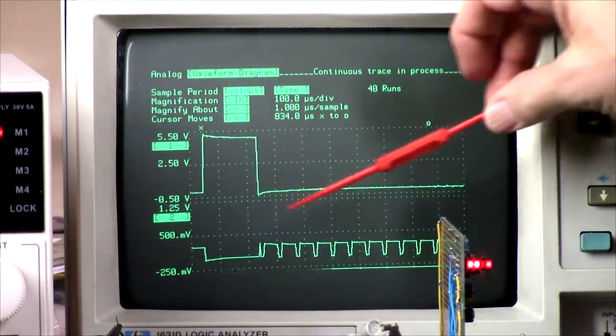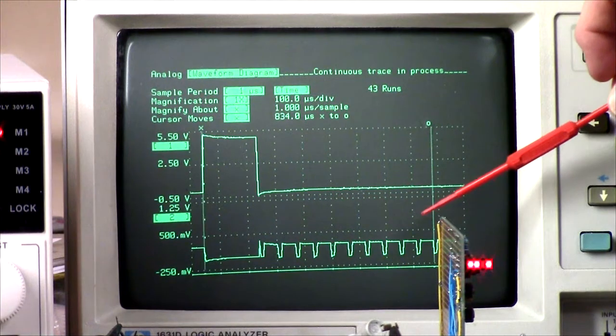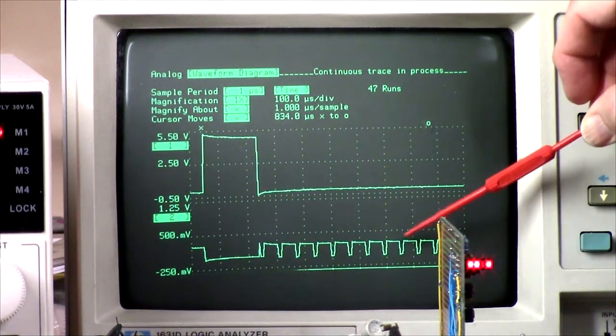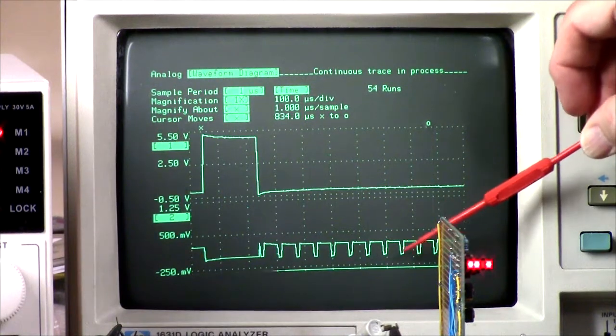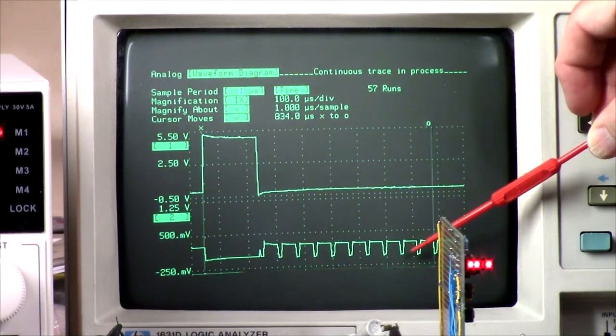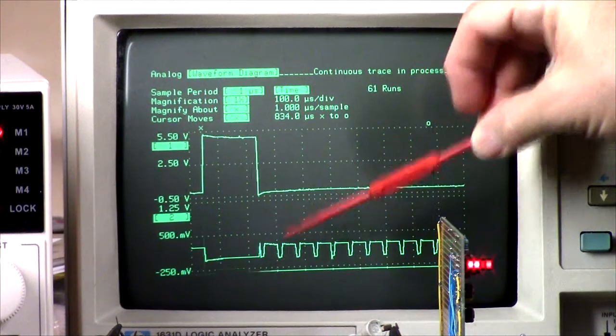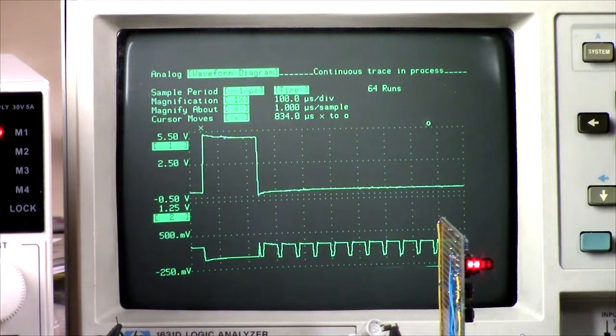So you can see here, we're at about 0.3 volts here, which is black level. And then the 0 volts is the sync level. And we have no white right now because, as I said before, the display is blanked.